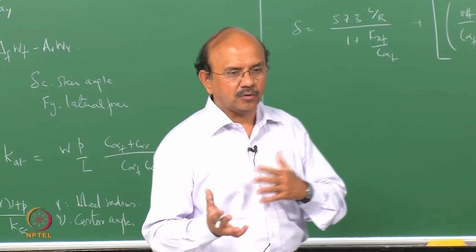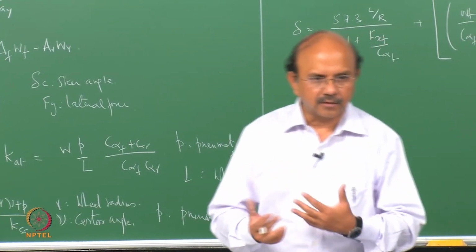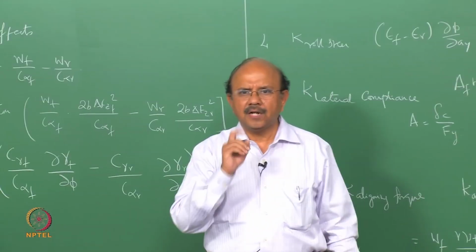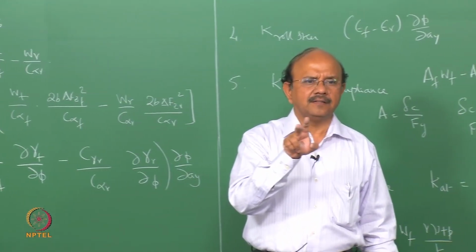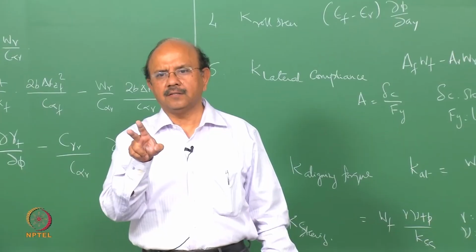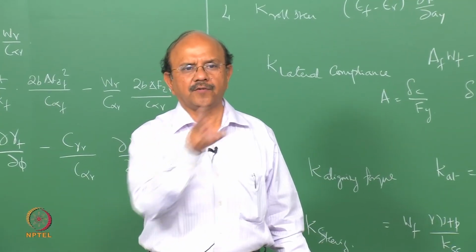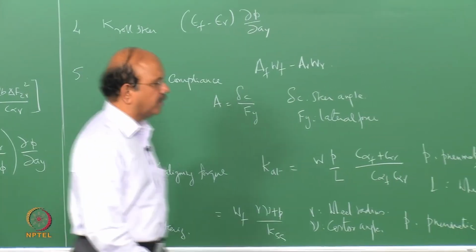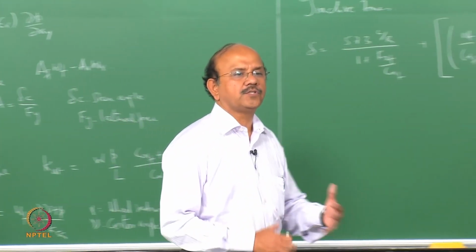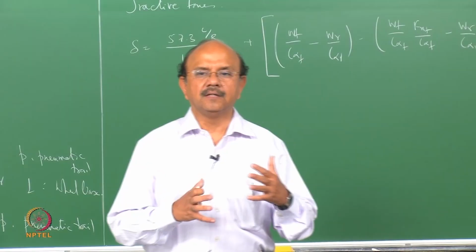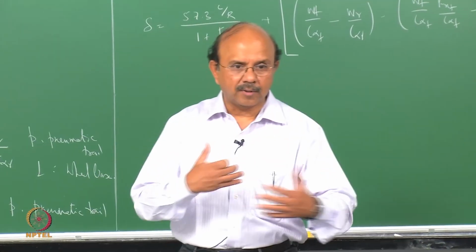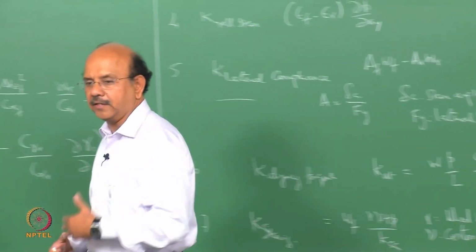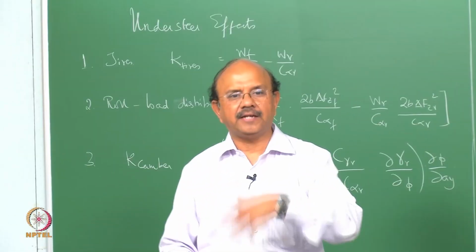Remember, we also defined when it is positive and negative and so on, right? So essentially what we are looking at is how the tire takes the force, changes the delta, and correspondingly whether it becomes understeer or oversteer. Then we looked at what is called the lateral compliant steer, and again, because the forces do not act exactly at the center and may cause a yaw because they may be off center, and depending upon whether the yaw center is at the front or the rear, the vehicle will turn to the right and the left and so on.